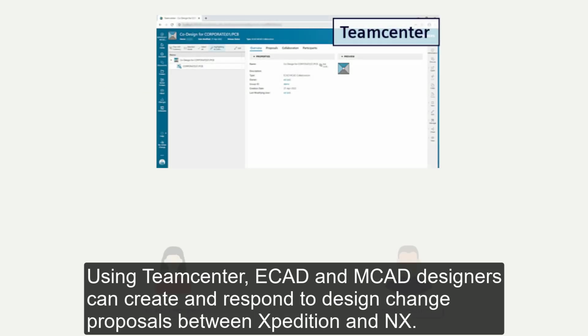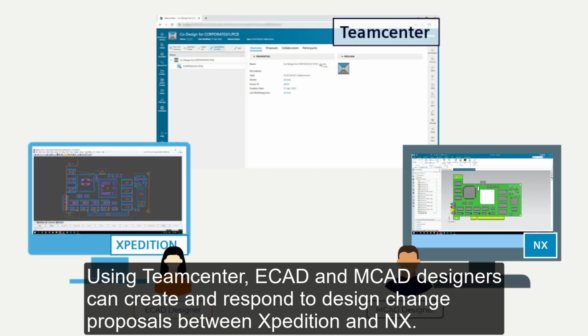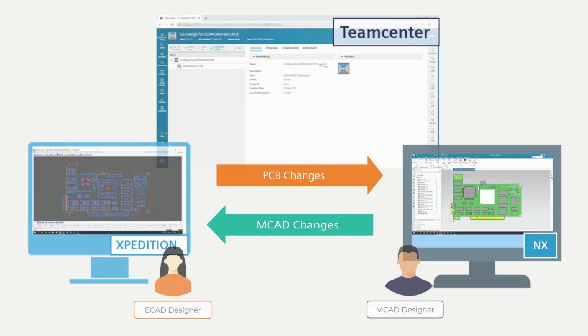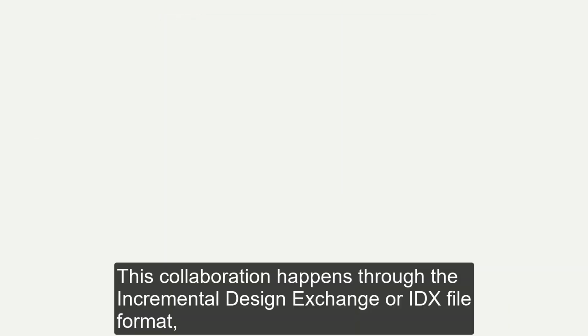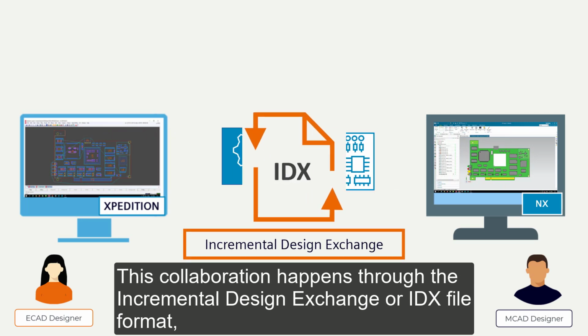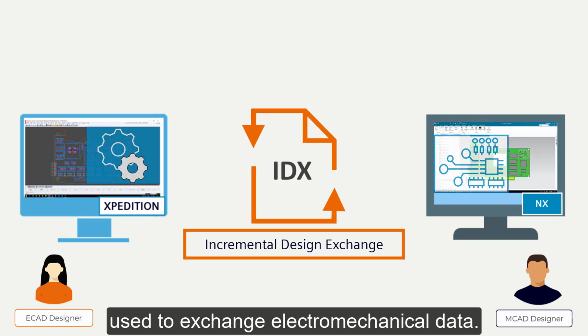Using Teamcenter, ECAD and MCAD designers can create and respond to design change proposals between Expedition and NX. This collaboration happens through the Incremental Design Exchange or IDX file format that is used to exchange the electromechanical data.